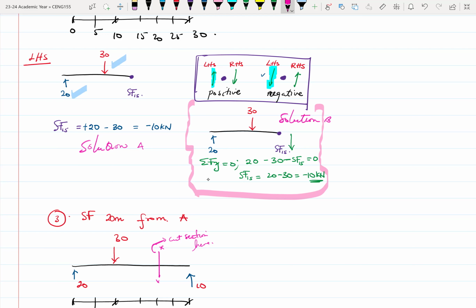So we only choose the area the force is acting more on. I don't get your question. If I'm to understand it in my own way, when you are looking for the shear forces, or axial or bending, whichever one you are looking at, you have to cut the beam into two parts at the point where you want to find the shear force, right?